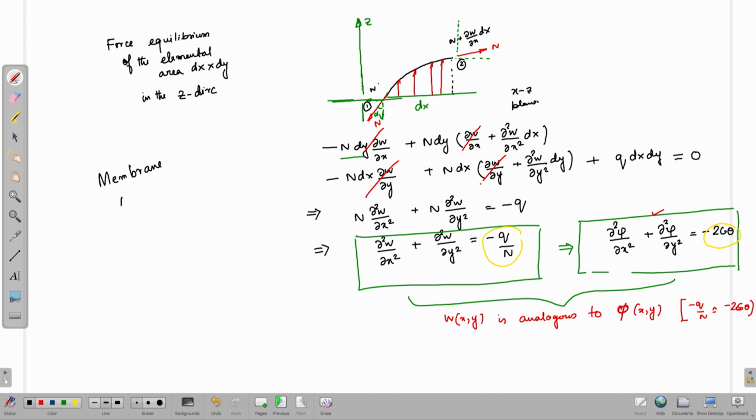This whole derivation that we have done, and this whole concept, is called membrane analogy. It is extremely beneficial practically to find the stress function for a non-circular cross section shaft and solve the torsion problem. It is even more useful when we deal with thin wall structures. So, we will see soon how effective membrane analogy is in the analysis of thin wall structures.